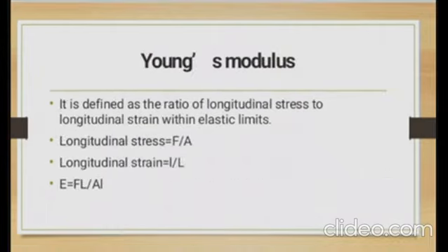Young's modulus. It is defined as the ratio of longitudinal stress to longitudinal strain within elastic limits. Longitudinal stress equals force by area. Longitudinal strain equals change in length by original length. E equals F L by A l.